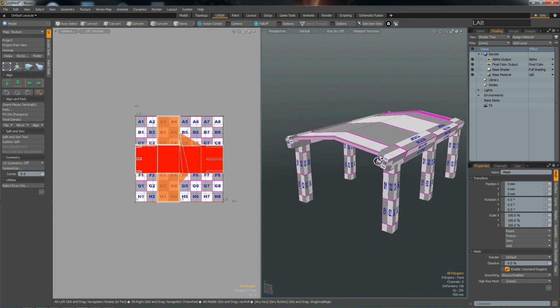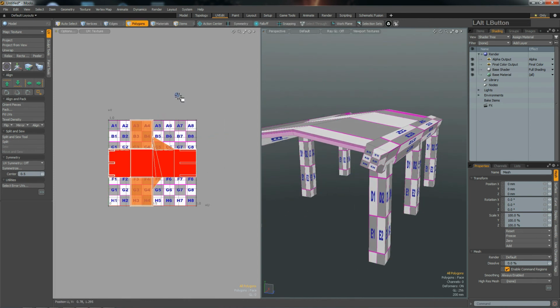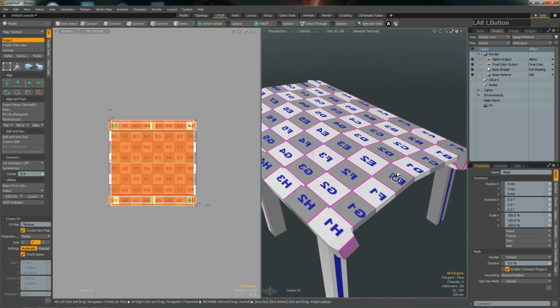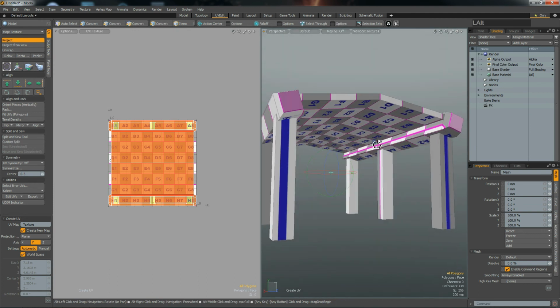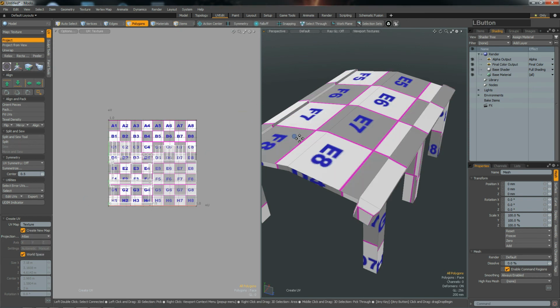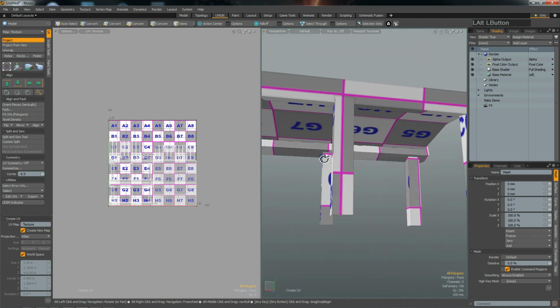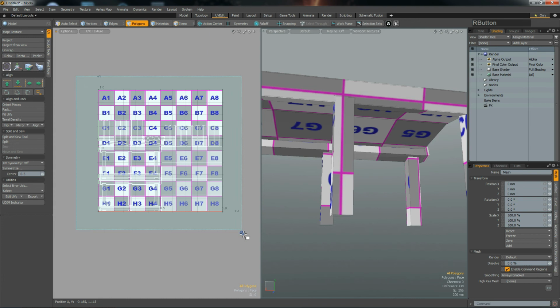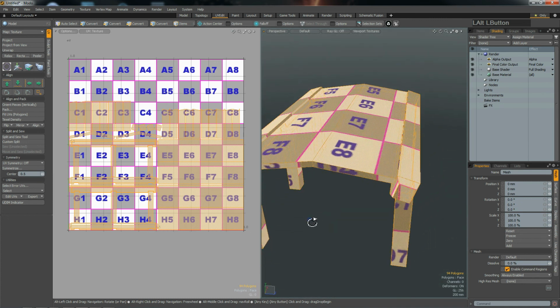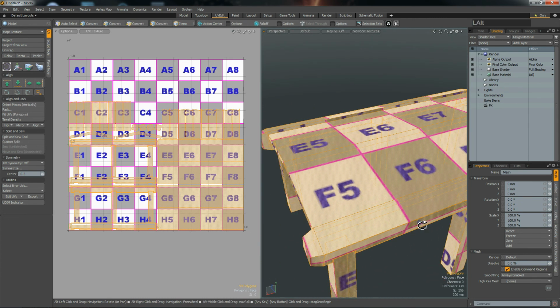Now just to make heads and tails of this, I have everything selected by having nothing selected, and here in my UV tools I choose projection, but not like this, not planar. This would be like planar from above, so everything on the side here is maximally stretched. We go for Atlas just to see where we are in terms of UV islands. So if I select them all, you can see them here. And that default unwrapping doesn't look too bad actually.